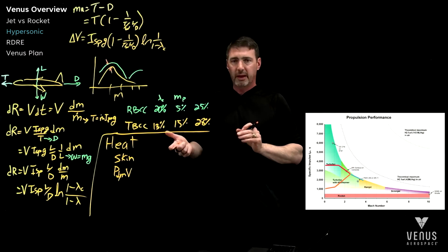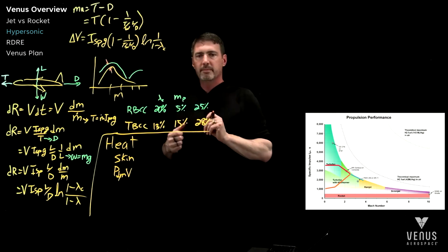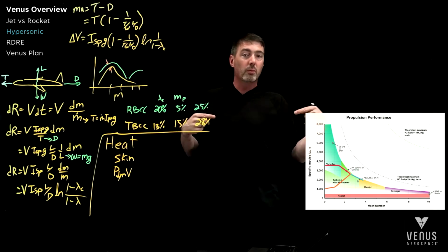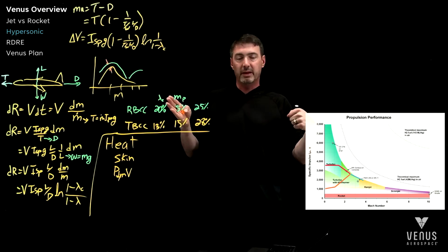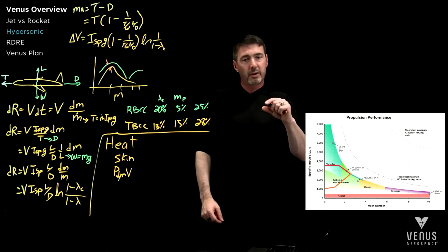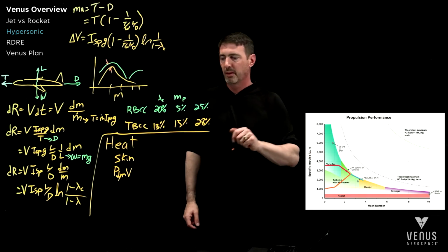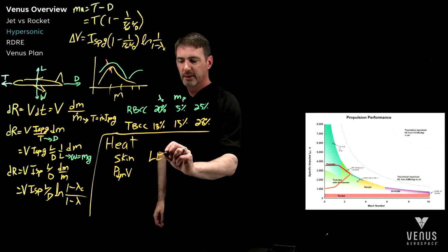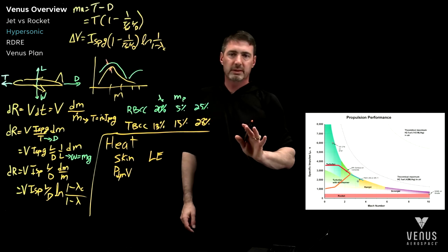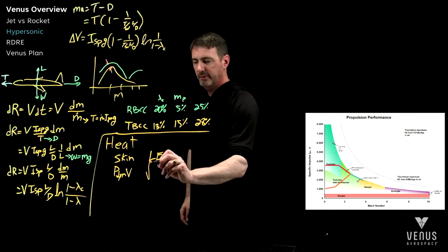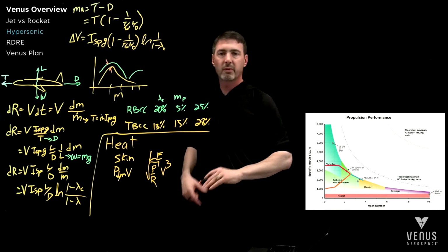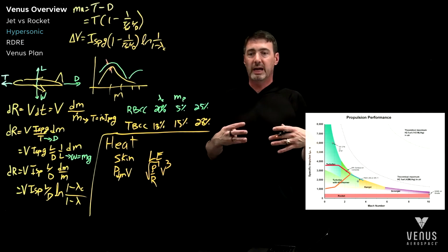And so you had, remember, those intercepts of, hey, what can my temperature handle? So you have that. Now, there's also the leading edge. And so anything, whether it's a nose or a wing, that air that is being compressed, right, there's a hot spot that builds up right at that stagnation point. And so that leading edge heat, we all have to pay attention to it. And in the end, some good formulas to correlate this is square root of density over the radius of curvature, velocity cubed. So what does this mean? This means blunt objects actually have less heating.